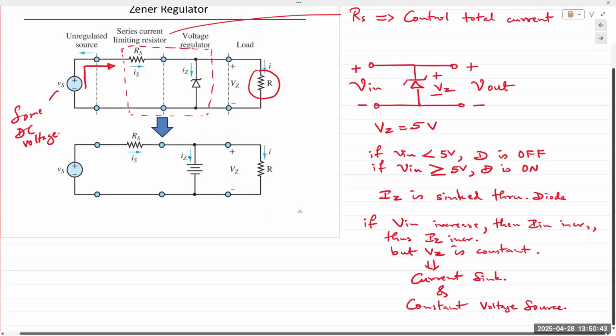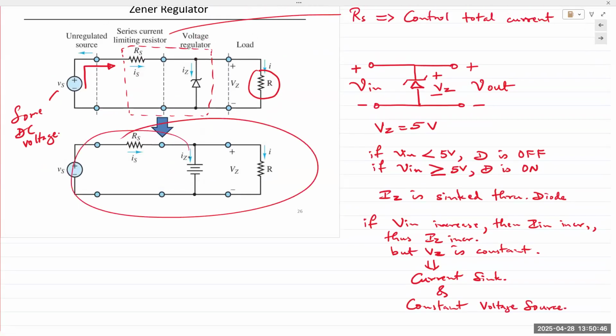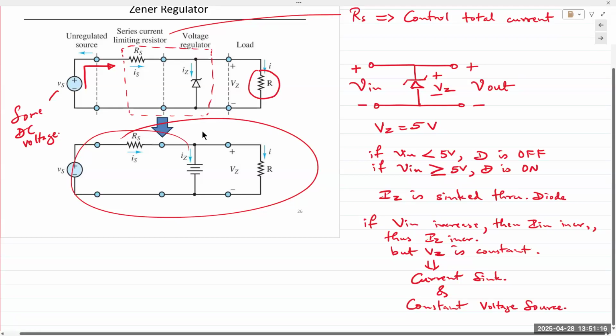Okay, let's look at this circuit now. So obviously, if you apply a voltage to this idealized circuit, there is no resistor to limit the current, right? So you would increase the voltage V in, output just keeps on increasing. Beyond a certain limit, the Zener diode could blow out, right? The Zener diode has a maximum power rating capability, PZ. That is the maximum current that the Zener diode can handle, okay? And that can range from milliwatts all the way up to like tens of watts, again, depending on the design and construction.